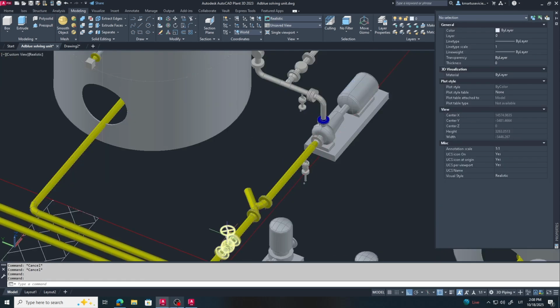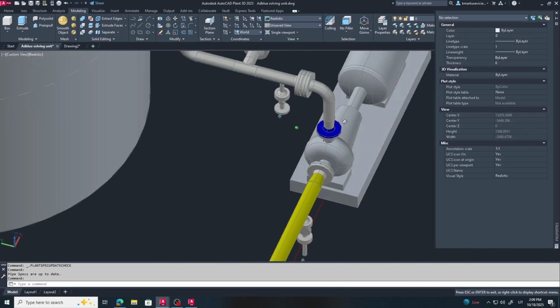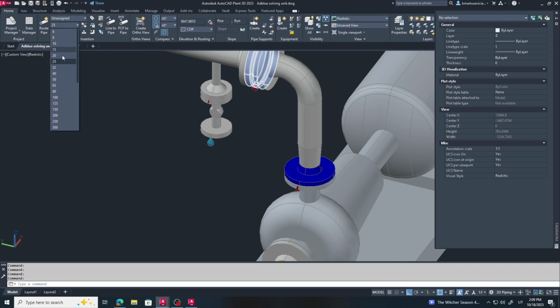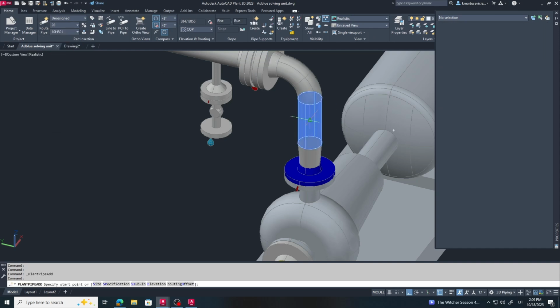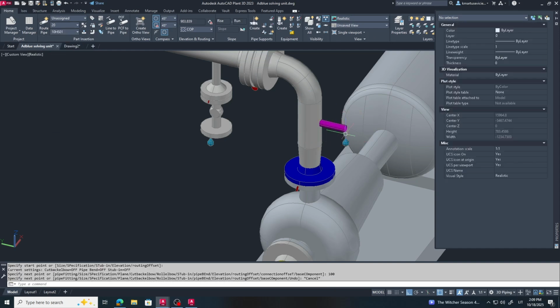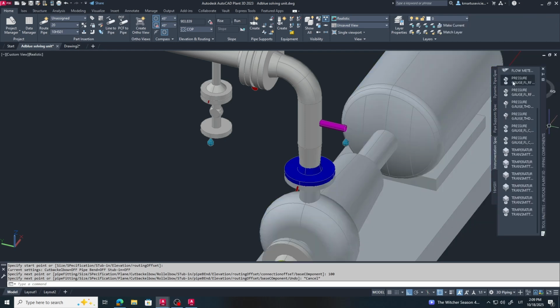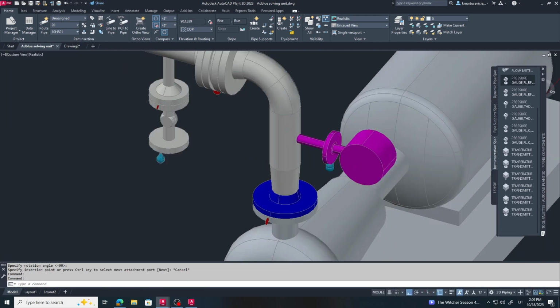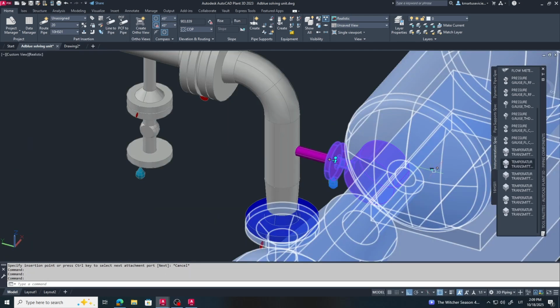Now it's time to add the pressure gauges on the lines so we can see what's happening in the system during operation. On the pump's discharge line, we install a pressure gauge to monitor the pressure the pump is creating. It helps us check if the pump is operating normally, detect blockages, and verify that the downstream system is not overloaded.